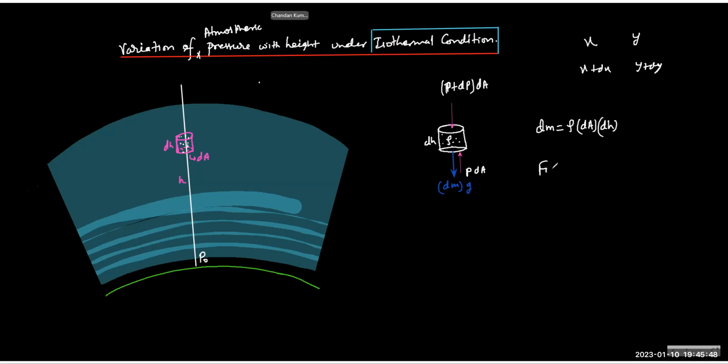So for equilibrium, what do we have to write? Tell me, guys. Rather, you all should write actually, because once you write, you will realize something. So please write the net force equals 0 and tell me what you are getting. dP by dh equals minus rho g.